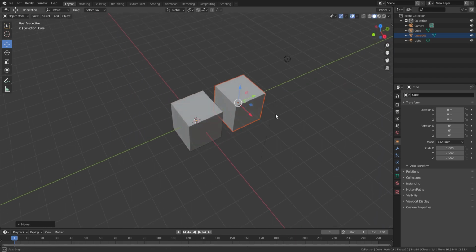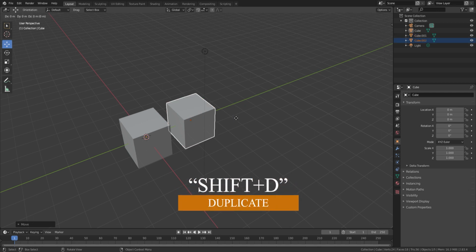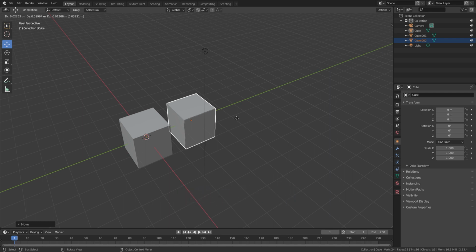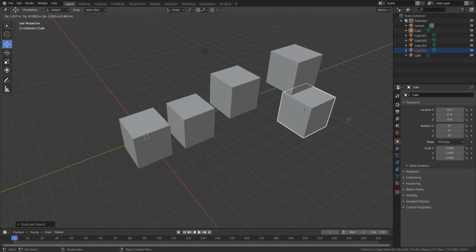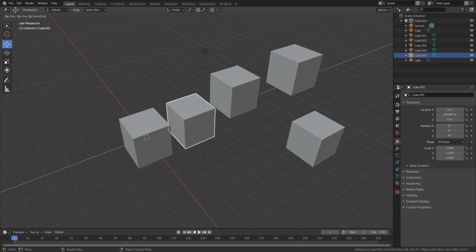There is a similar shortcut for such a case, which is the command Shift-D. By pressing these two buttons, we are able to freely move the clone in the space, which is synchronized with the camera, so it's not a precise solution but fast. Therefore, we can move it all around. To be more accurate, after selecting and pressing Shift-D and adding an axis, we can only move the cube in a certain direction. These are the X, Y, Z directions and the X, Y, Z buttons which belong to them. For example, if you want to move on the Y-axis, just press Y, and whatever you do after that, the cube won't be able to move anywhere else but on the Y-axis.